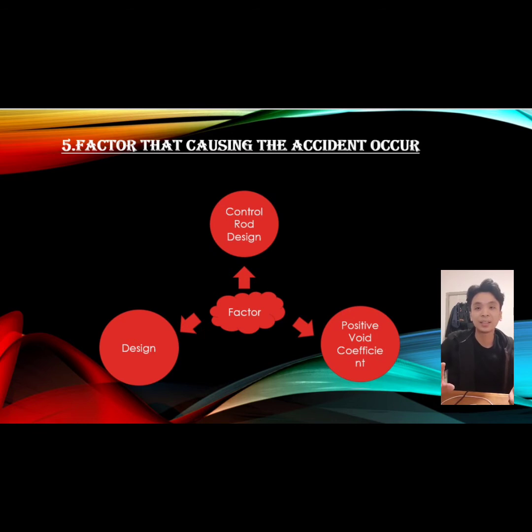The next thing is the positive void coefficient. The reactor had a dangerously high positive reactivity void coefficient. The void coefficient is a calculation of how the reactor's water coolant responds to increased steam formation. Most other reactor designs have a negative void coefficient. The rate of nuclear reaction slows as steam bubbles form in the coolant, so fewer neutrons are slowed down as the steam void increases.